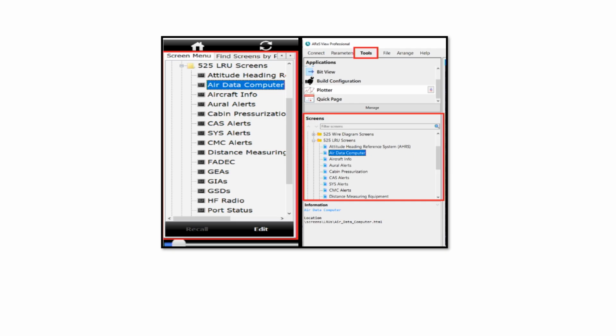AReS 3 will have greater functionality and data collection due to improvements for more data inputs, including ARINC 429 and ARINC 717, ARINC 825 or CAN bus, discrete, and will enable a serial communication protocol that enables 2 or more devices to send and receive data simultaneously.